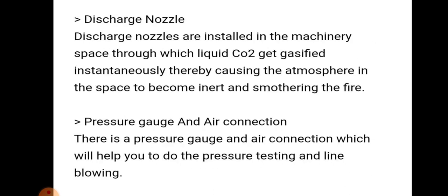Discharge nozzles are installed in the machinery space, through which liquid CO2 gets gasified instantaneously, thereby causing the atmosphere in the space to become inert and smothering the fire.